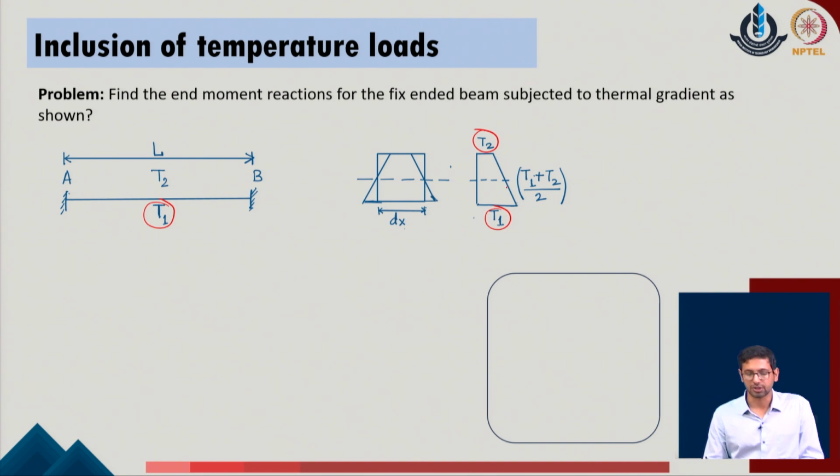Now, what we can understand from this is that as the system is subjected to a temperature gradient between the top and the bottom flanges, the system will undergo some amount of bending, as the bottom fibers will experience more stretching or more tension, whereas the top fibers will be subjected to less deformation, such that the overall deformation considers that one end of the given system is under compression and one end of the system is under tension. And under the application of this kind of primary behavior, the system will experience a condition which is identically defined in the standard bending theory.